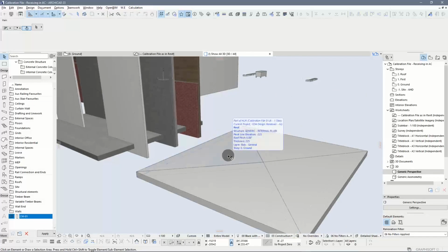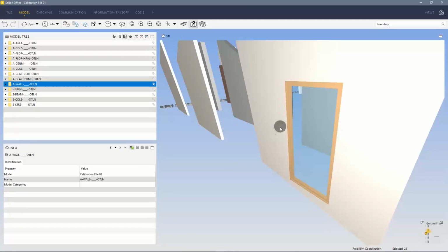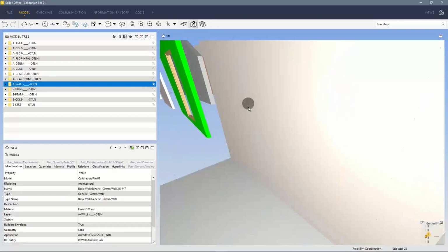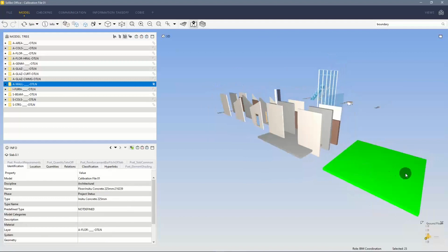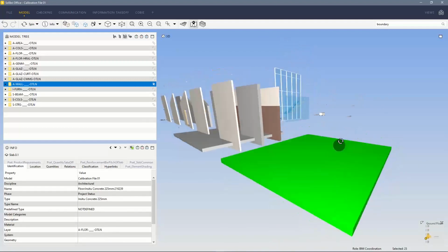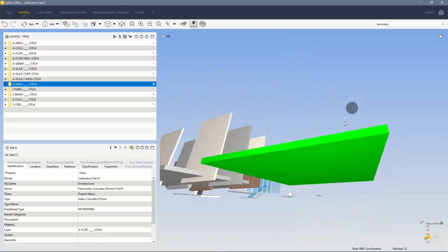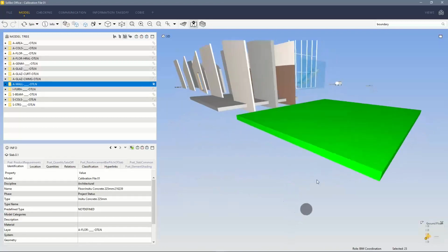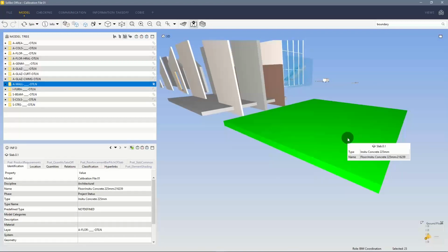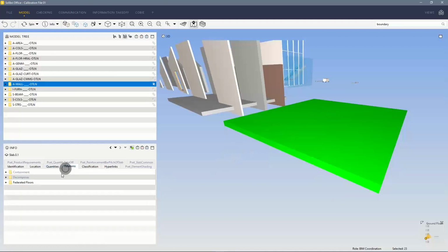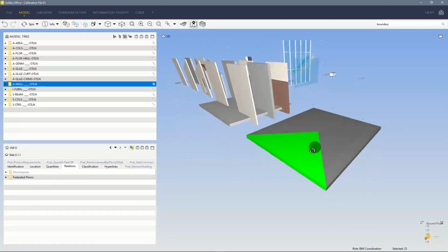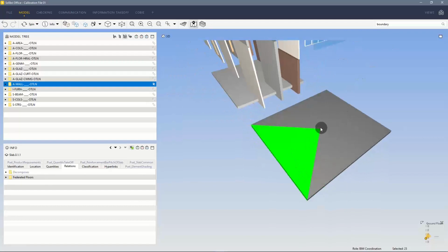And then this one here, which is actually, if you go and take a look at the IFC, I know that was created with the Revit floor tool. Let me show you. And it's creating just a regular floor. The only difference, which is a very common thing, is that this one here is actually a slab with a slope to the center. So in that particular case, that'll be decomposed into 4 different slabs, all of them sloping to the center for a drainage point, let's say.